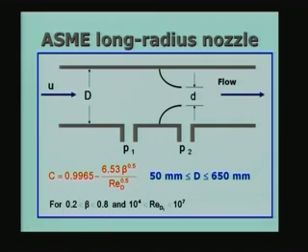P is larger. Therefore, in most applications where we want to use a variable area metering device for measuring velocity or flow rate, we must make sure that the delta P which you are going to obtain is large enough to be measured easily by using an available pressure measuring device.